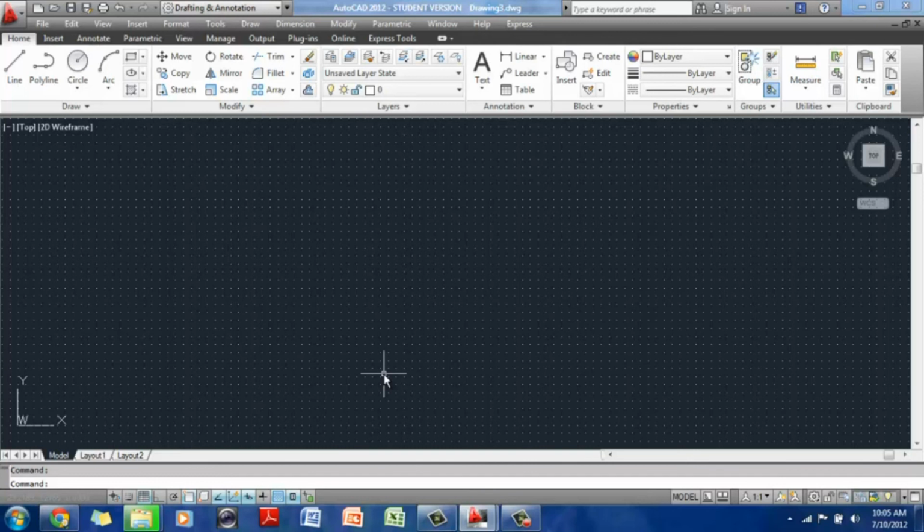So what we're going to do now is we're going to create a template file. This is for architectural drafting files. You can create any number of template files that you want depending on the nature of your work. So you could have a template file for an architectural project, a different one for a civil engineering project. You can have different templates for architectural units, which is your feet and inches units, which is what we mostly use in the United States for architectural drawing. You can also have a template file that uses decimal units, which is the metric system.